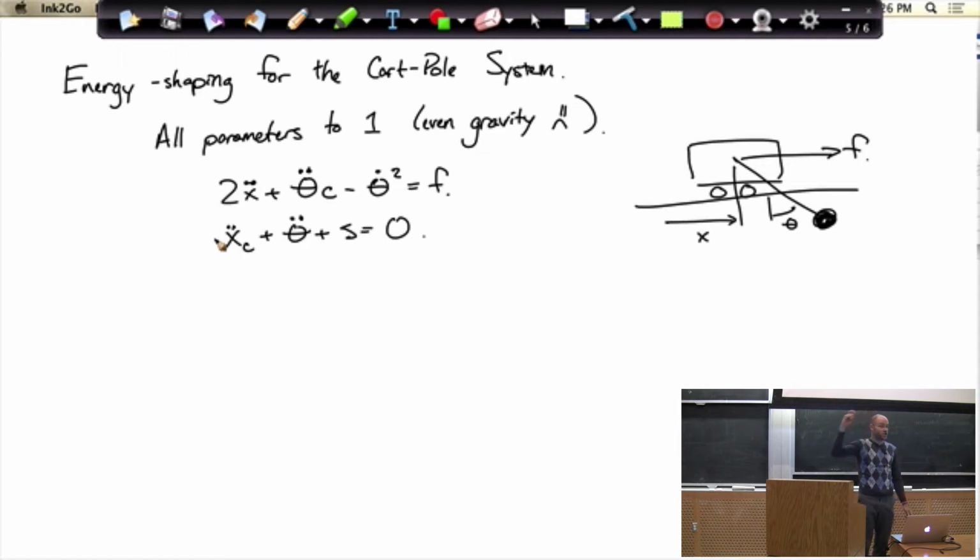So what we're going to do is only reason about the energy of the pendulum still, where it has this nice homoclinic orbit. We're going to try to make sure that whatever the cart's doing, the pendulum lands on its homoclinic orbit and gets up to its upright. And then we'll try to do some extra little work at the end to make sure the cart does the right thing. Because the total energy is not that hard to write out algebraically, but it's hard to reason about a simple solution that gets to some unstable fixed point.